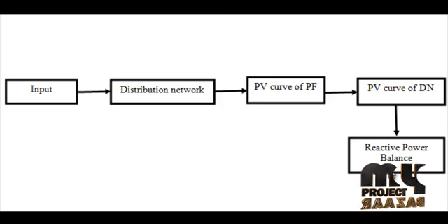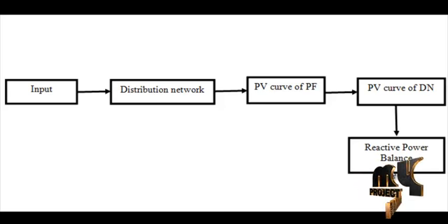The cross point in the right section is the stable equilibrium point and the cross point in the left section is the unstable equilibrium point. There are stable equilibrium points for all 4 power factors, but the operating voltage is reduced with reduced power factor. A stable equilibrium point between the load reactive power voltage curve and the grid reactive power voltage curve indicates the bus 3 static voltage stability condition.